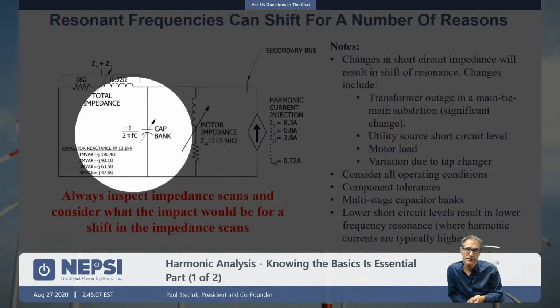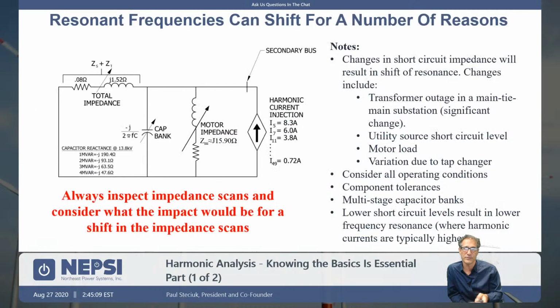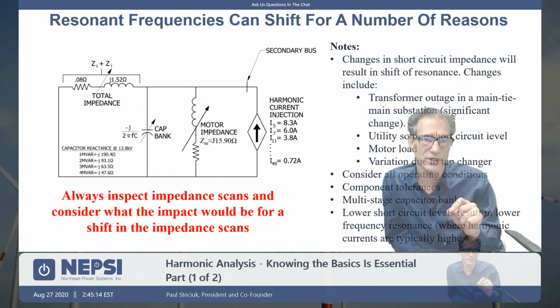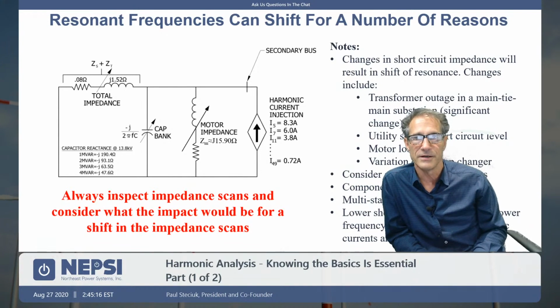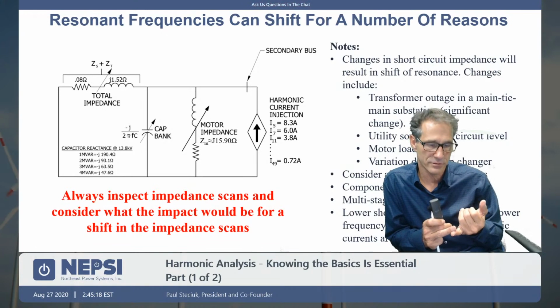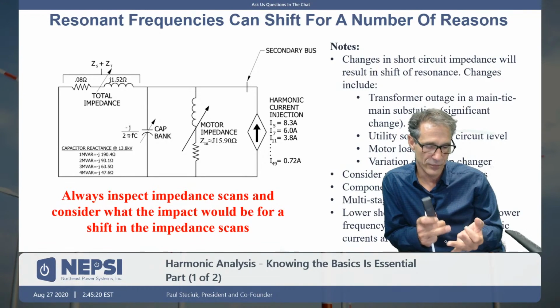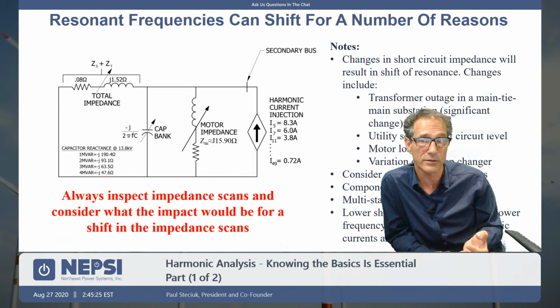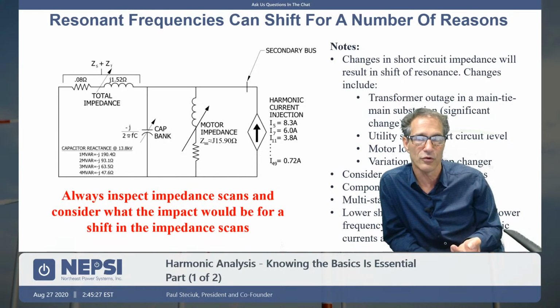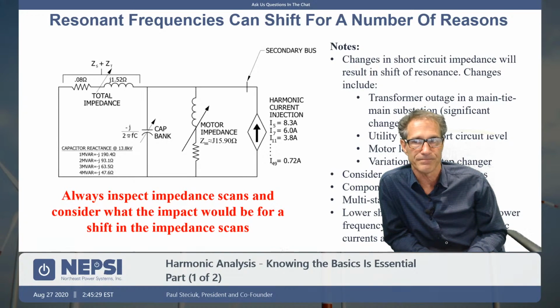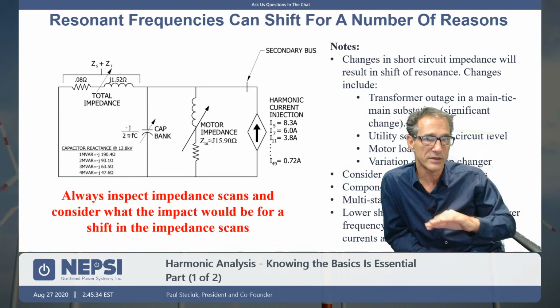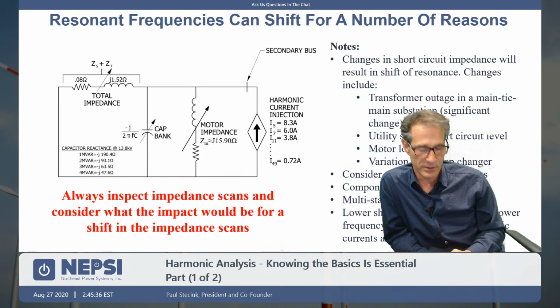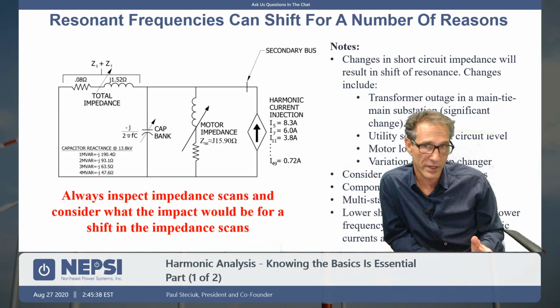And then finally you have the impedance of the source. This is the transmission grid. Remember, this is a relatively small value, but it does change. The value does change depending upon local generation. Think about, you have the renewable plants, you got coal plants that come in and out depending upon politics to some degree. Are those coal plants running or not? So depending upon transmission outages, the impedance of the source can easily change. So you have to consider these when you're doing your analysis.